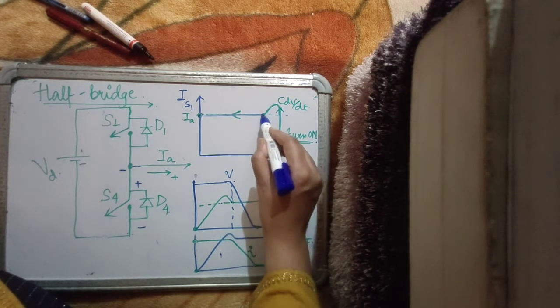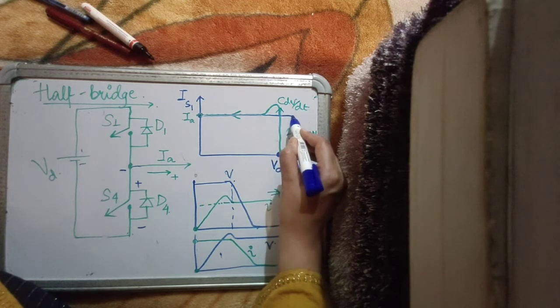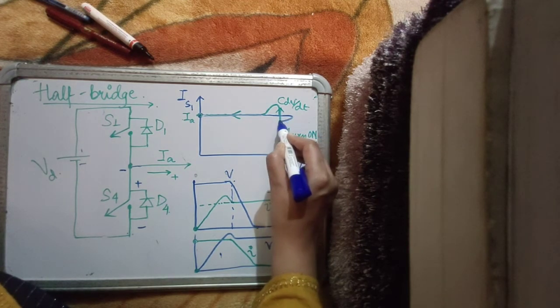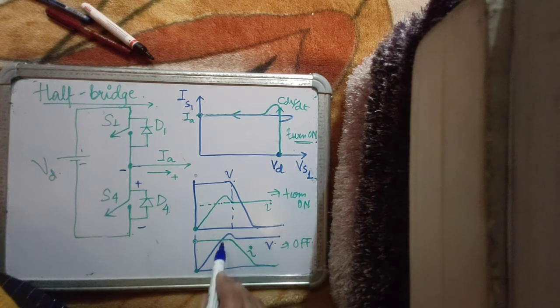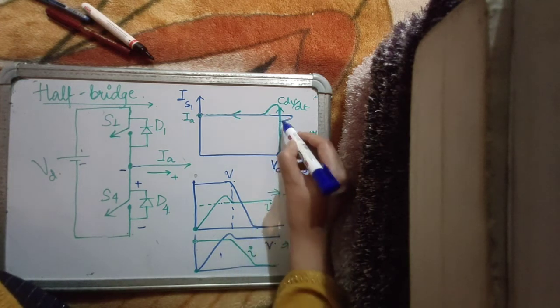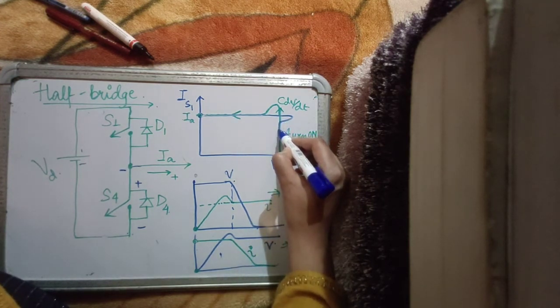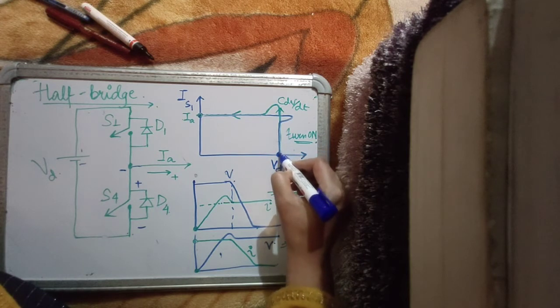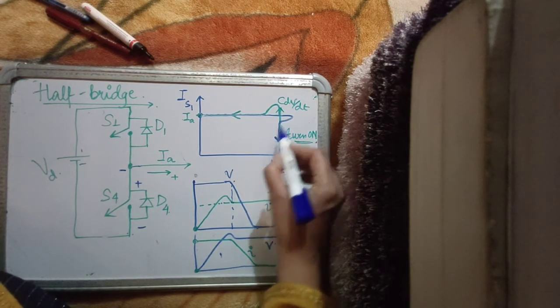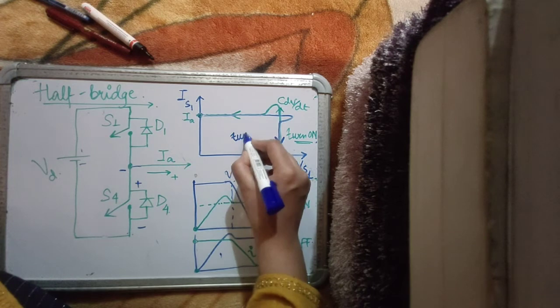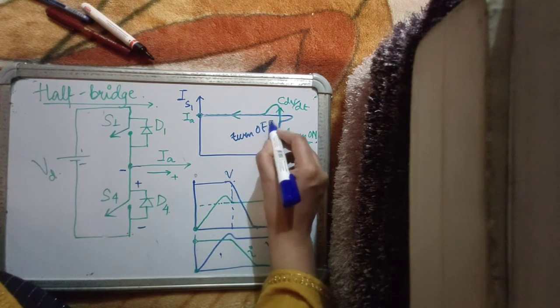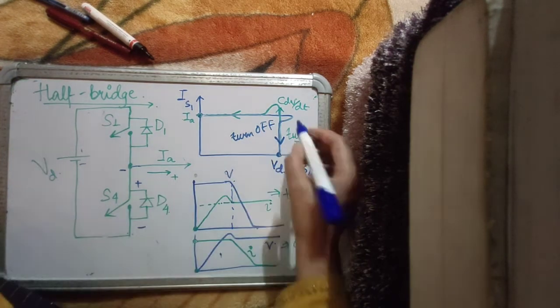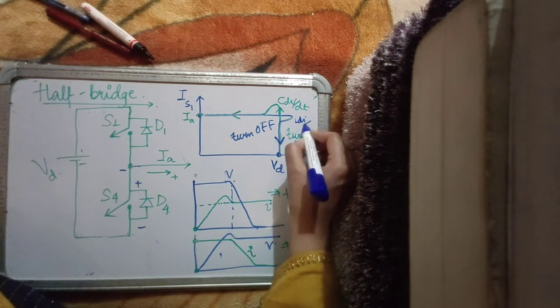If this is the VDC value, the voltage exceeds that value and then settles back to VDC, and the current then starts falling. So the current then begins to fall at constant voltage. The blue curve is the curve for turn off, right? And this kick is an L di by dt kick in the voltage.